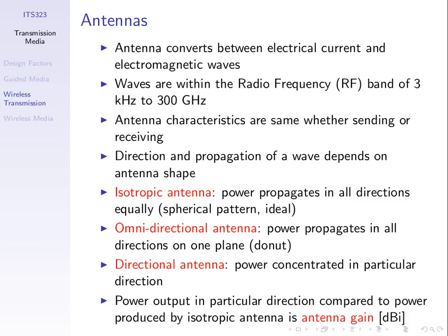Watts. Remember, we can talk about volts, but when we talk about communication systems, we'll usually use the units of watts. 1 watt, 1 megawatt, 1 microwatt, and so on. So when I talk about signal strength, the signal magnitude, the signal power, I mean measured in watts. With an isotropic antenna, we start with the transmit power, say PT, and that energy disperses.